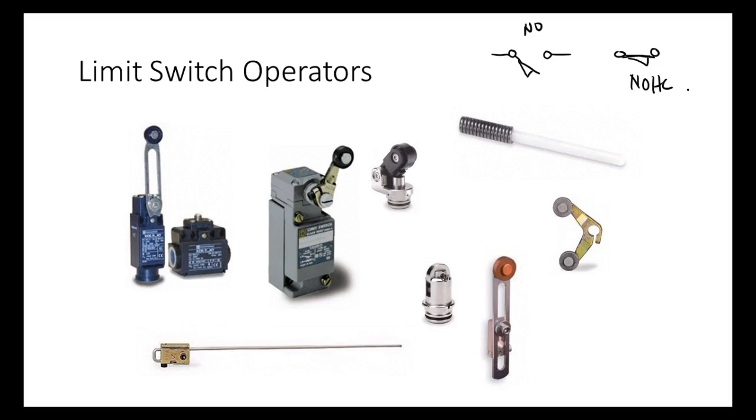Normally we draw these limit switches at the device's home position or origin position. If it's got a limit switch that indicates it's up against where we park it, then when we turn it on, it's going to be closed, right? So in your diagram, it would be drawn like this. This would be a normally closed. So I'd come up above it, right? Gravity's trying to close it, so it's already closed. So this would be normally closed.